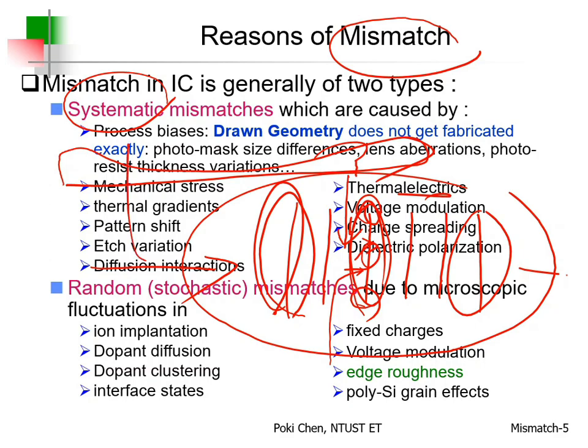That is the so-called systematic mismatch. All right? That is your destiny. 那是你的命运。If you are here, I mean to the border, to the boundary of the wafer, you will get thicker oxidation. If you are lucky in the middle, then you will get thinner oxidation. I mean the average value, okay? Then that is the destiny. You cannot change it. That is the so-called systematic mismatches. We have a lot of issues according to that.